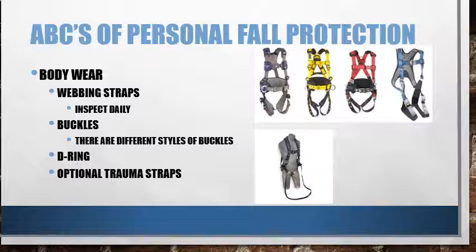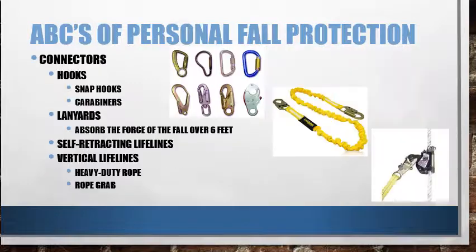And then there's also a thing called trauma straps, which are an optional bit of bodywear. If you were to fall and be suspended, trauma straps allow you to lower something for your foot to rest on. So you're not just having all that weight holding you on your pelvic area and keeping your legs dangling, which can be uncomfortable while you're being rescued.